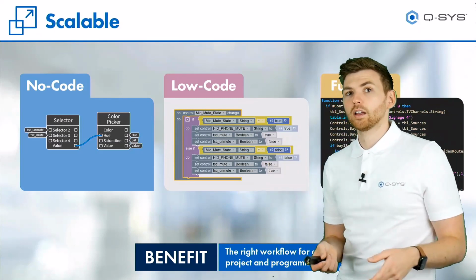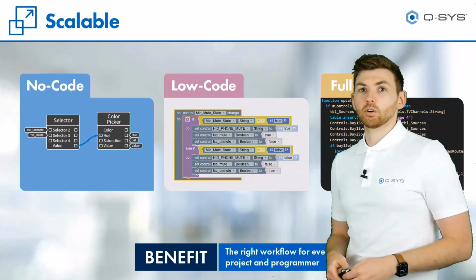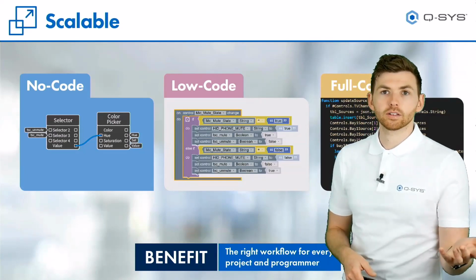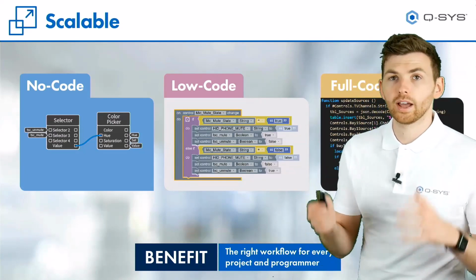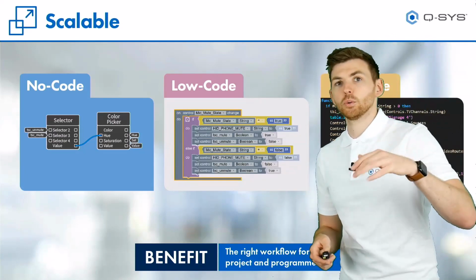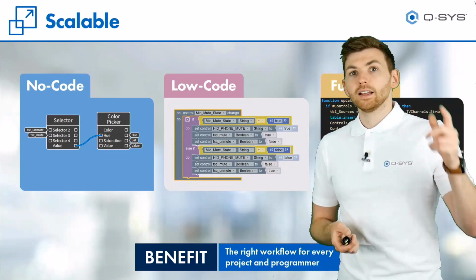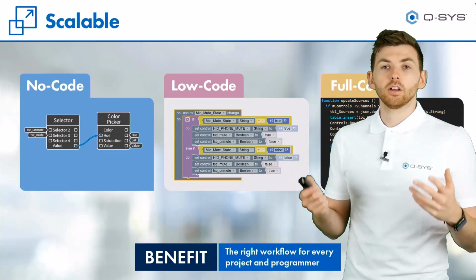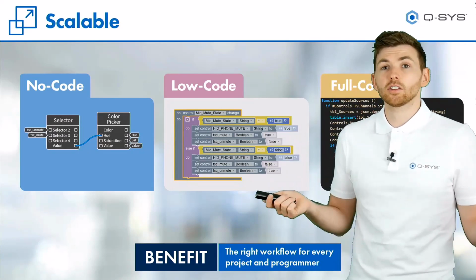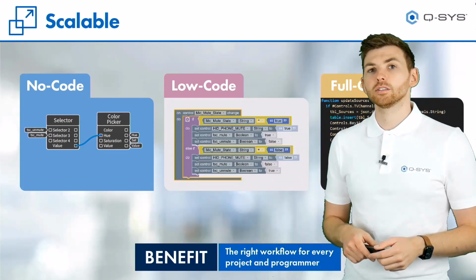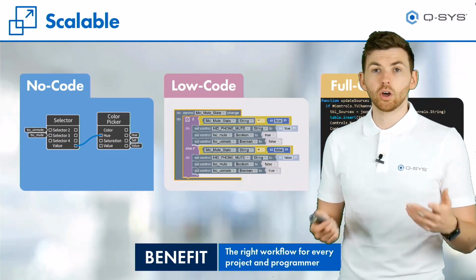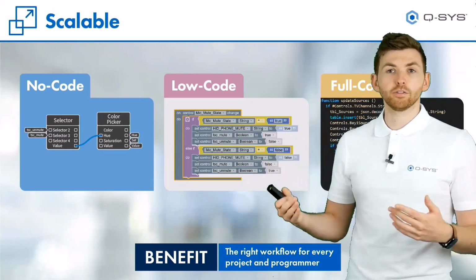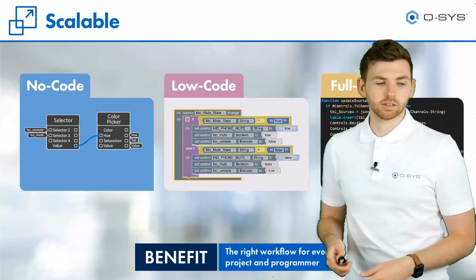You could do that with an upgraded Core Nano or a Core 8 Flex, and in that case you'd be talking about 2 or 3 Teams systems. You could do more than that. Really the limitation is 32 peripherals for the whole core. Now the Core 110 and up don't have a peripheral limit in total, and there's no imposed limit for Teams UCI controls. You could do a lot of them. Realistically, you're going to be limited by other factors before you get limited by that, things like AEC that we've spoken about.